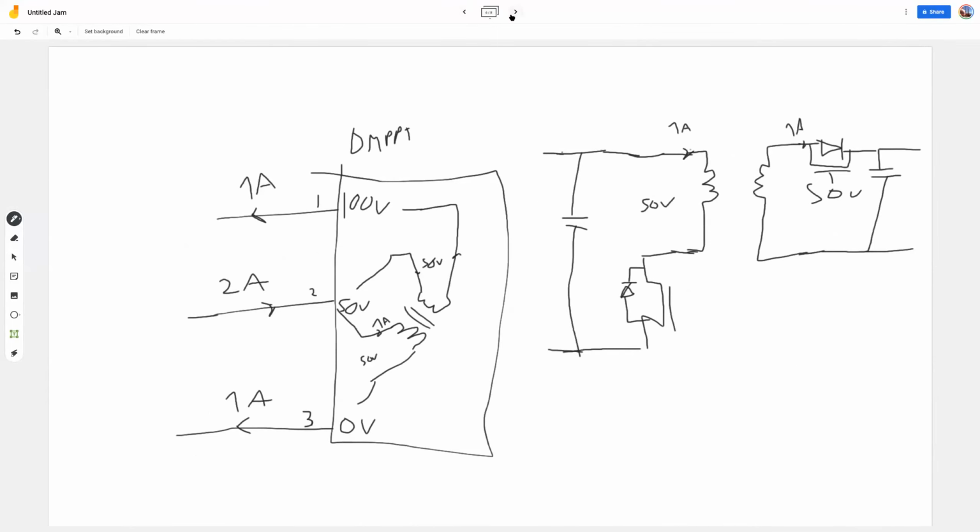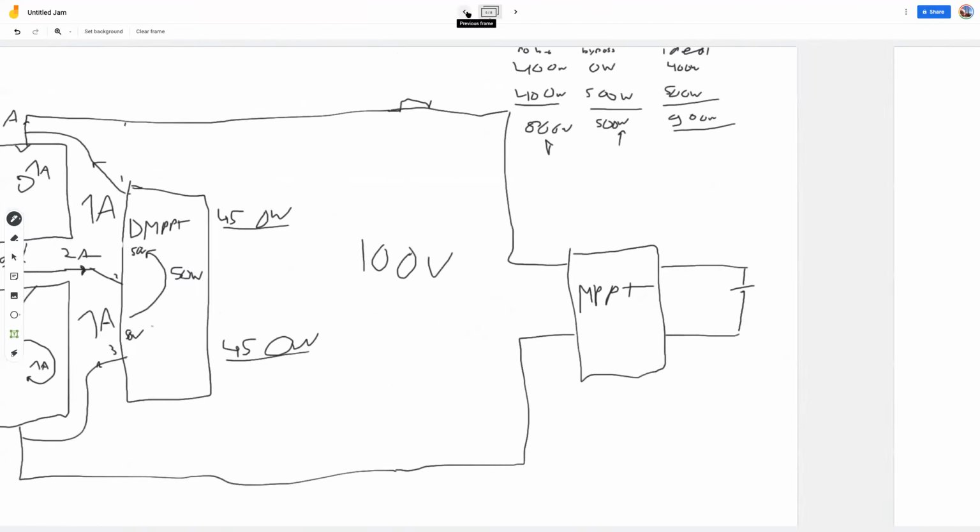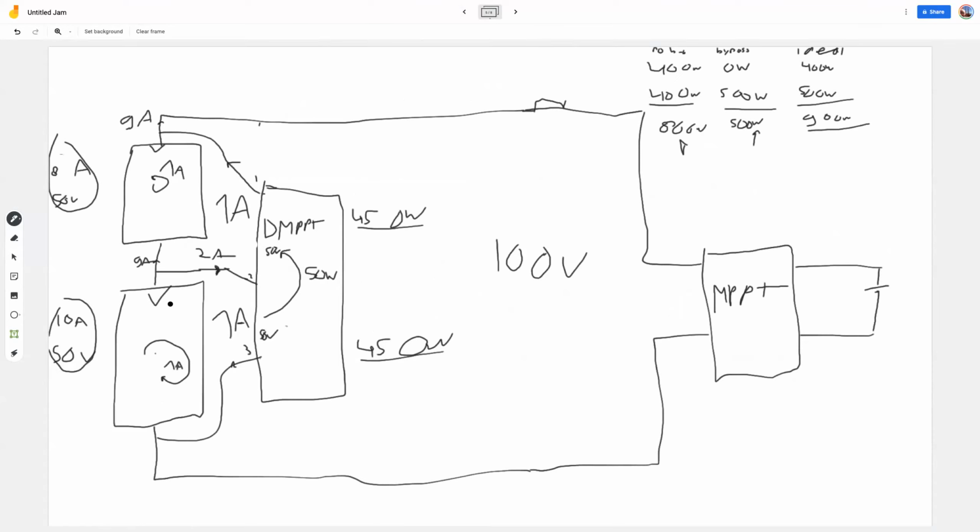Let's say we have this example, with two 50-volt arrays put in series, making a 100-volt array, going through the MPPT. If you get a normal MPPT and you boost from 100 volts to 120, it should be around 99%. I have one that is a little bit more efficient, but it should be around 99% with the average solar car MPPT that you can buy. If you go from 50 to 120 volt with a normal MPPT, it's usually around 98% efficient.